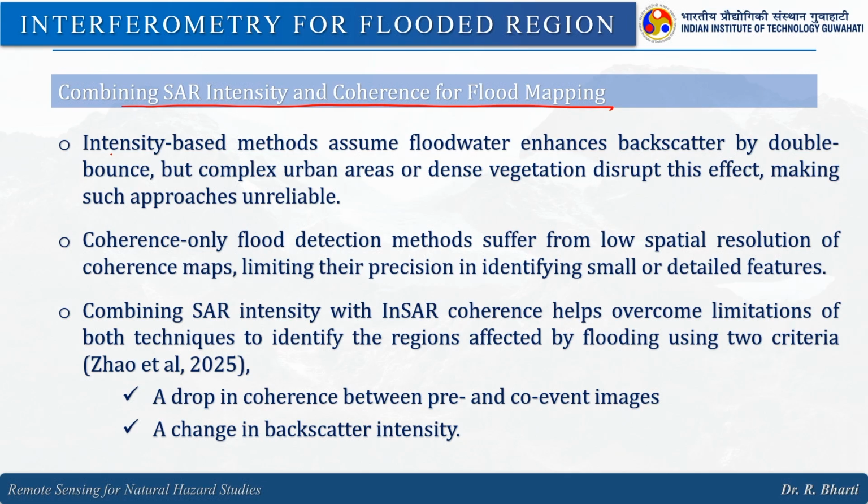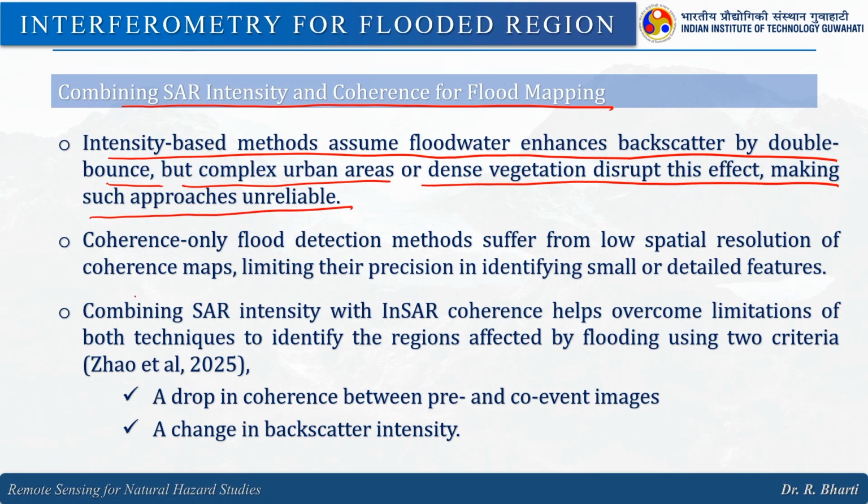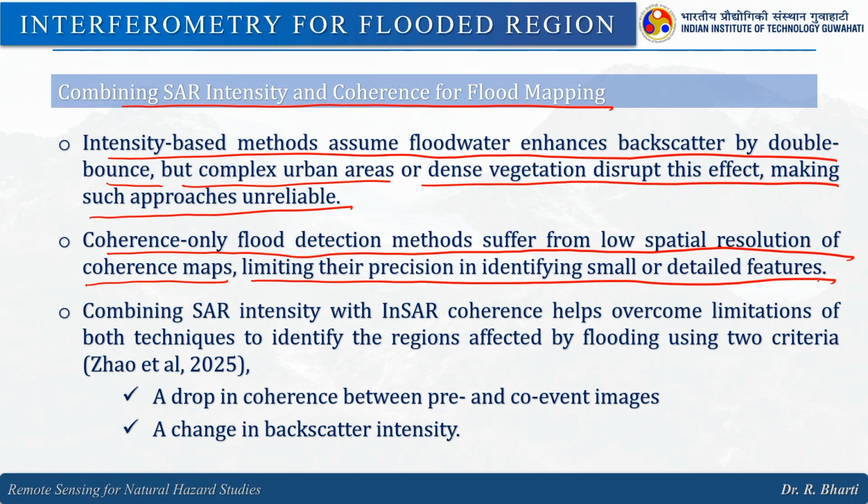Now, combining SAR intensity and coherence for flood mapping. So, we continue that one. Intensity based methods assume fresh water enhances backscatter by double bounce, but complex urban areas or dense vegetation disrupt this effect, making such approaches unreliable. Coherence only flood detection methods suffer from the low spatial resolution of coherence maps, limiting their precision in identifying small or detailed features. Combining SAR intensity with SAR coherence helps to overcome these limitations.